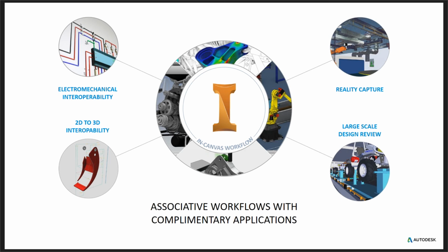There have been a lot of improvements over the last couple of years in regards to bringing some of that legacy 2D AutoCAD data, or even from other sources, into Inventor. So there are some DWG underlay technologies in Inventor to be able to bring some of these legacy drawings in. I see it being used a lot for sheet metal. You can bring in some flat patterns, and you can generate that 3D geometry pretty seamlessly by using some of the tools built into Inventor.